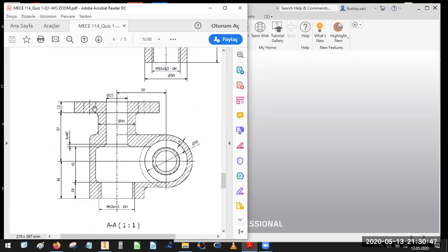Here we have two revolve sections. The first thing, I would like to have one revolve section, like this. I will just follow something like this. If you want, you can just consider this part with a full revolve section. For this, please ignore this portion. We will just make a hole inside and we will add the threaded section here.